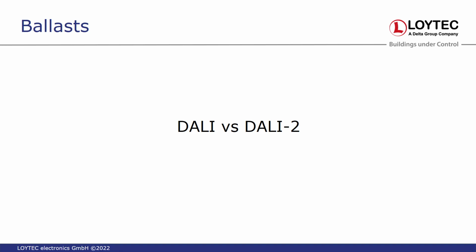This was not standardized in DALI 1, but regarding ballasts for the LDALI, it doesn't matter. But when you have a combination of ballasts and sensors, DALI 2, then the ballast might be confused by the other sensors on the channel, not the LDALI. We have seen such sites where this was an issue.